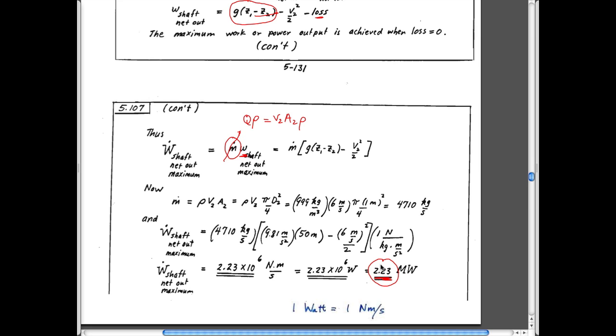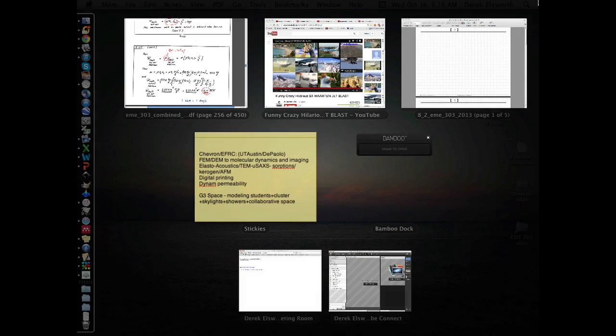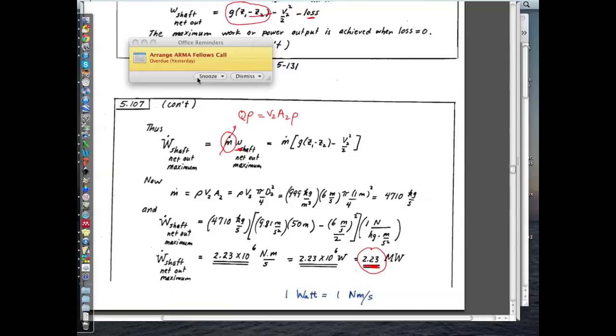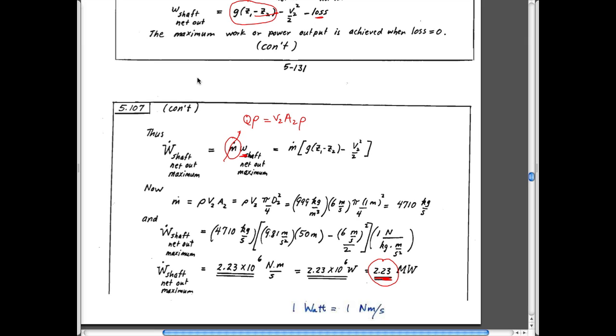All right. Went longer than I thought, but that's okay. So the other things, well, first I should ask. So everyone okay with that? So two expressions. The energy equation is really just Bernoulli equation written slightly differently that allows you to have viscous flows, flows that aren't inviscid, that have some loss attached to them, and also allows you to put some extra energy into the system in terms of a pump head or recover energy from the system in terms of a turbine.